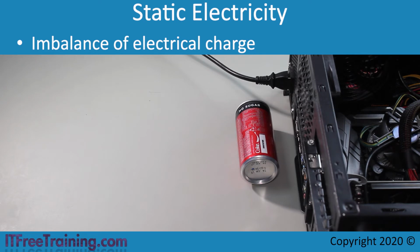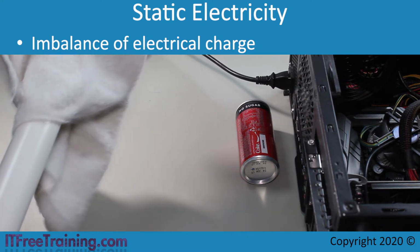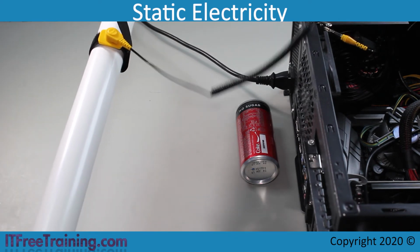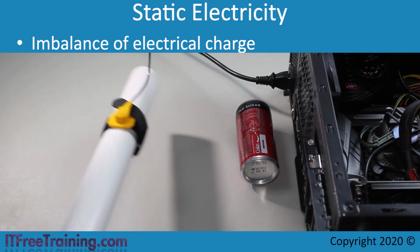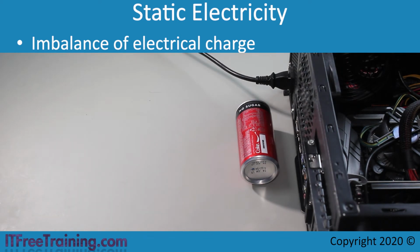To demonstrate how to remove static electricity, I will once again charge up the PVC pipe. Once the PVC pipe is charged up, I will attach an anti-static wristband to the PVC pipe. Once the anti-static wristband is attached, notice that when I place the PVC pipe near the can, it is no longer attracted to the pipe. Essentially what has happened is static charge in the PVC pipe has traveled over the wristband to the computer case, effectively causing the pipe to have a neutral charge.